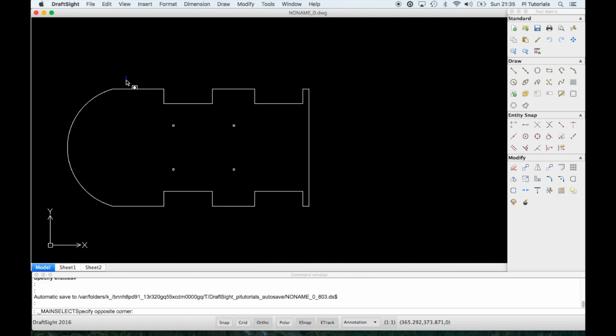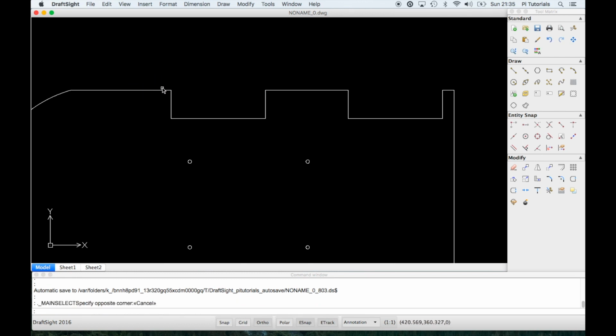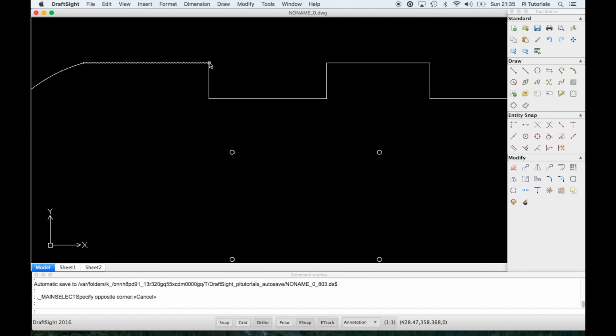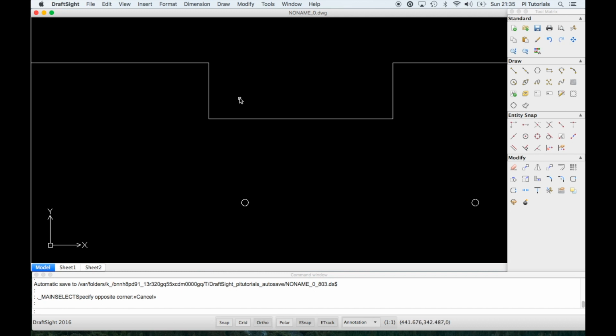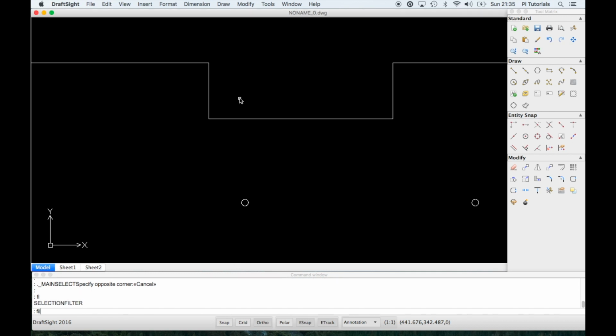Right, what next? Chamfer and fillet, I think. So I've got some sharp edges here. Maybe I don't want a sharp edge, so I can fillet it or chamfer it. So let's try fillet first. FI short for fillet. Oh no, it's not. It's filter. So fillet. Let's type fillet. F-I-L-L-E-T, space.